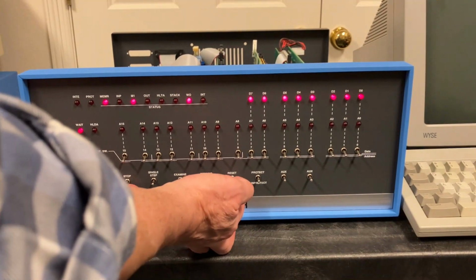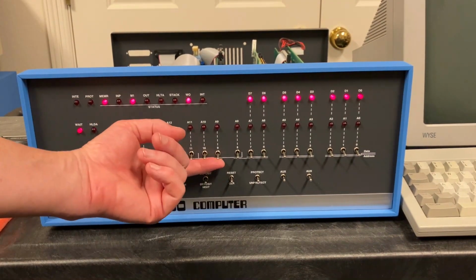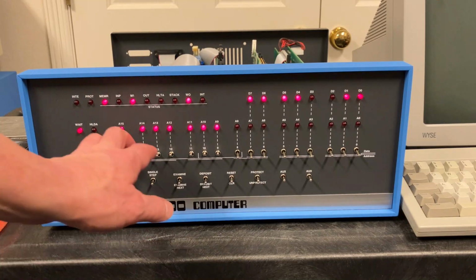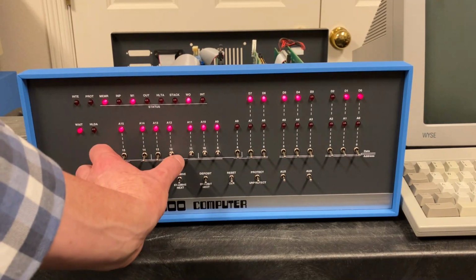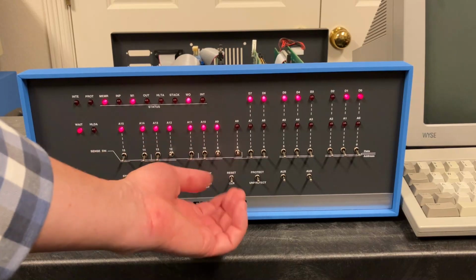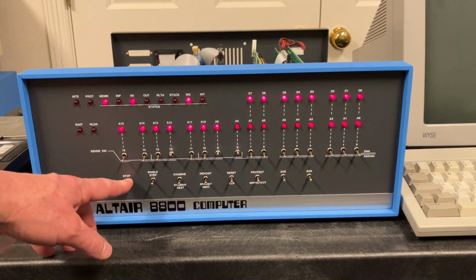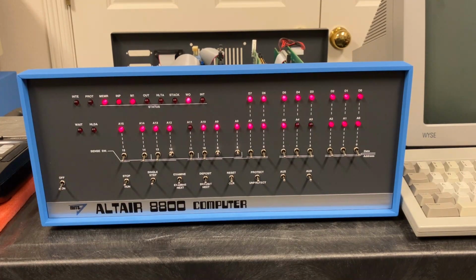Give it a reset. Examine FE00, that's the multi-boot loader. Tell it once BASIC's up that you're going to run from a 2SIO. Tell it with a 3 here that we're going to run from cassette. I'm going to release the cassette to start playing and hit run. And off it goes. At this point, it's going to load BASIC. This will take about 4.5 minutes. And I'll come back when that's about done and we'll just quickly demonstrate that it's up and running.